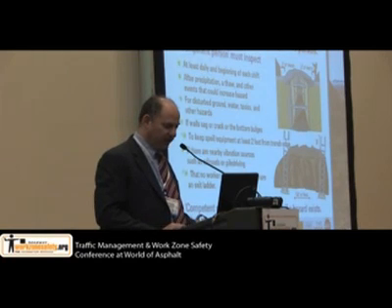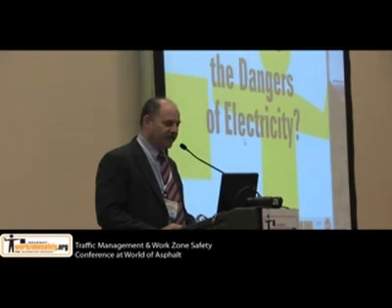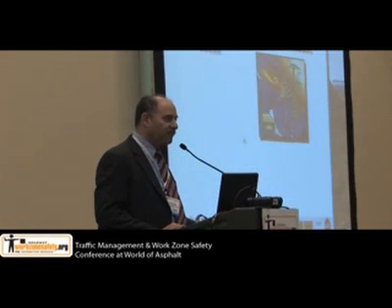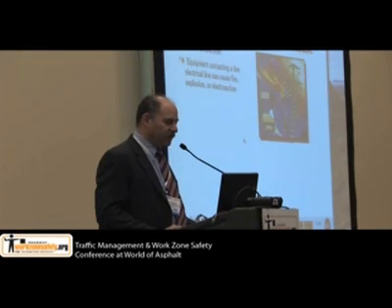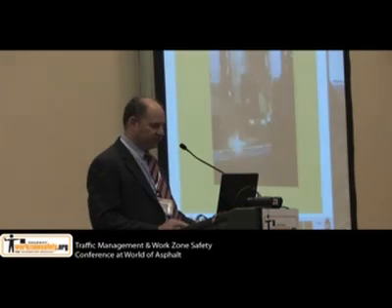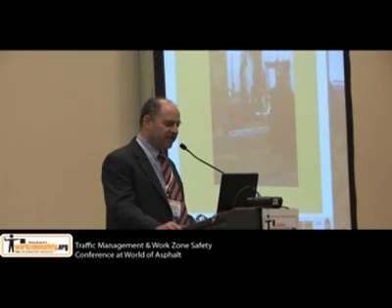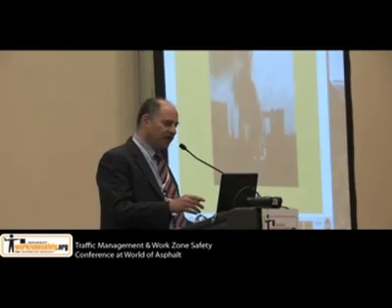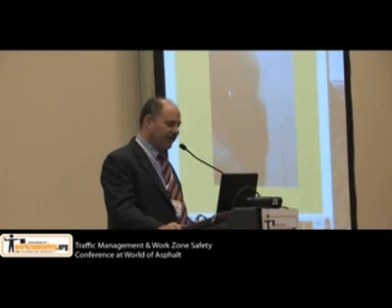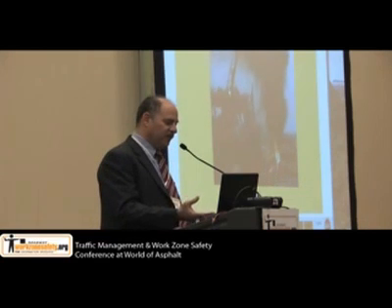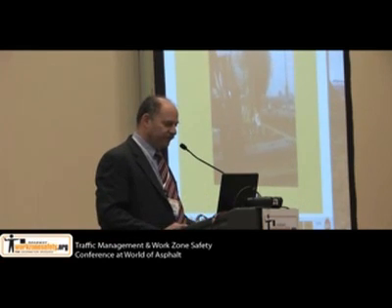I'll briefly go over another one, electrical hazards. A number of workers every year in road construction get killed, primarily from contact with an overhead power line. So we show you, for example, this video that was done by OSHA showing a power line contact. You can see, as you look up here, that the drop line from this crane is touching the power line, and as a result, you can see the outriggers are catching on fire.